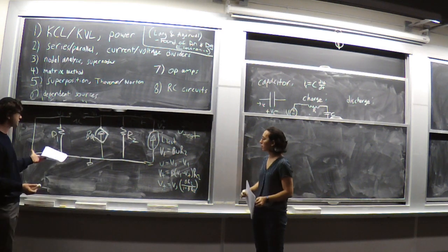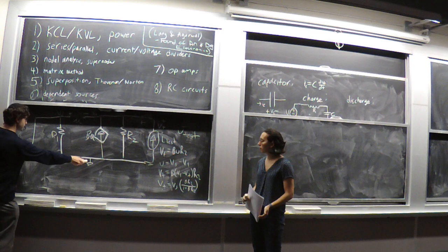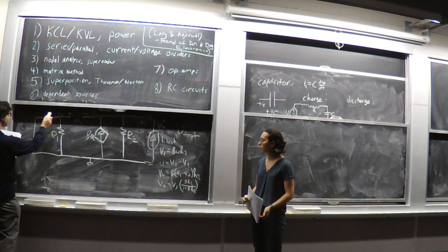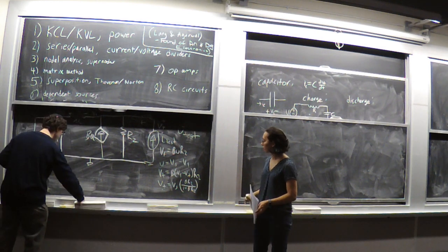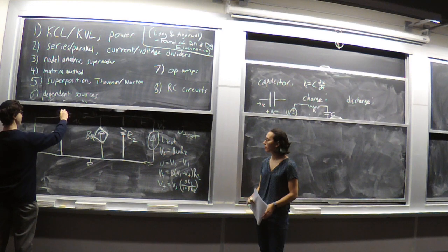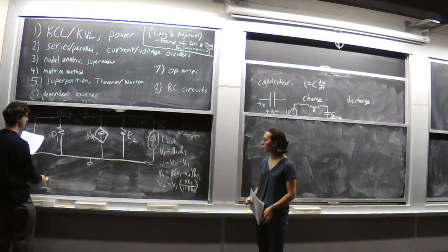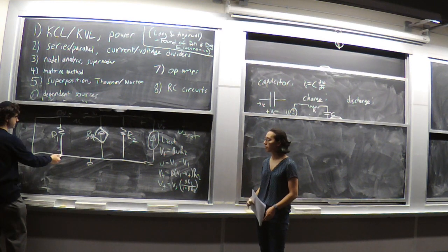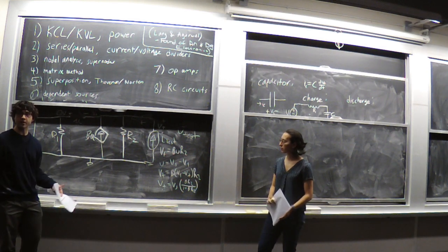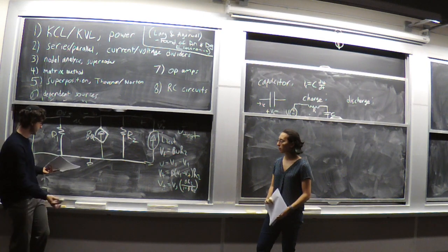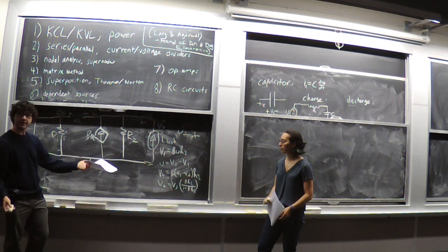This analysis is also a bit simpler, because notice this resistor R1, this ground goes all the way around and up here. This is no longer VS, it's just 0 volts now, because it's still the same ground node. You might wonder what R1 does now. Well, one way to think about it is that if there's 0 volts up here and 0 volts up here, there's no voltage drop across the resistor R1. And if there's no voltage drop, there's also no current. So we can just forget it exists. It's irrelevant to the circuit. So the only thing we have to analyze is this side.